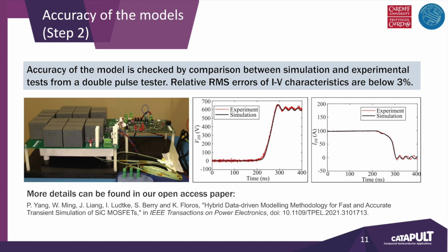We tested our characterization and modeling results based on artificial neural networks. What you find is that the error of the IV curve during the off process, the relative RMS error, is less than 3%. We compared this with some commercial software, like software from Keysight, for modeling characterization. We found their error is around probably 15, even 20%, but we significantly reduced the error during the on and off. And in terms of speed, we improved the speed of simulation by more than 50%.